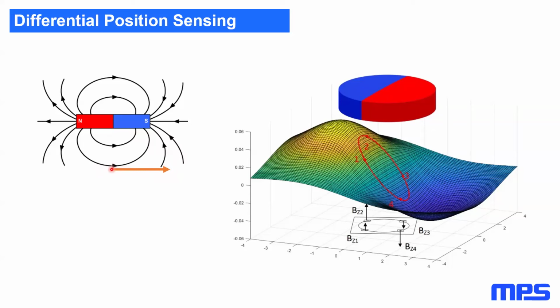We would have a Hall cell that's sensitive in the direction of the die. But we can do the same thing by looking at two parts of the vertical field. So instead of looking at the horizontal field, now we're going to take two sensors. We're going to put one over here and one over here. And here we see a magnetic field pointing upward. Here we see a magnetic field pointing downward. And hey, it's kind of reminiscent of that current sensor. We have a differential pair.